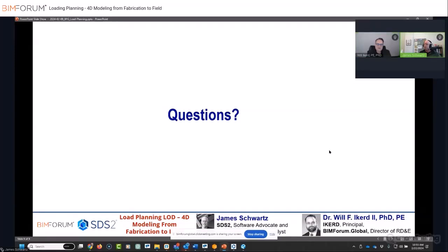So does the product have a free viewer level where you've got someone who's doing the loading, but then someone else needs to consume it? Export the IFC, and they can open it up in any IFC reader, from BIM Vision to BIM Plus to Trimble Connect to whatever reads an IFC 2X3. Navisworks, if that's what you have in house, right?